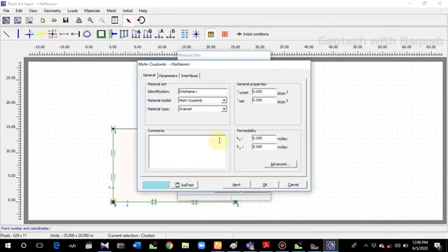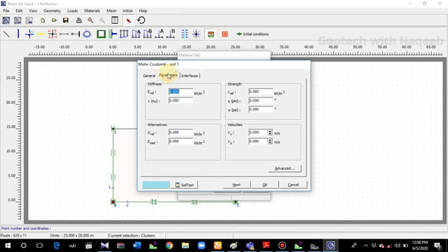Now I will go to the material properties. We'll define a material. The same material properties I will use in another software. So let it be soil 1. It's a homogeneous embankment. So Mohr Coulomb model, drained condition, the unsaturated unit weight is 17 and saturated is 19. So no need to provide these permeability values. Okay, now I will provide the stiffness, that is 4000.